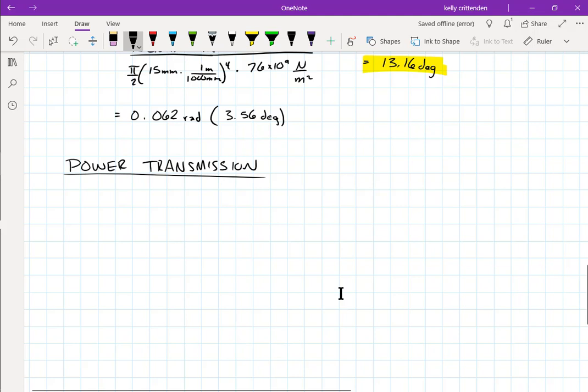We're going to take a pretty simple approach to this power transmission. We're going to assume that power is conserved. If we do want to take into account the idea that there are losses in our system, which there would be, you're not going to have 100% power transmission from your motor over to whatever it's driving. But we'll just say that the machine or the system is some percent efficient. Like it might be 80% efficient or whatever. And so if you put in 100 horsepower, then you get 80 horsepower out. And so we'll just kind of keep it pretty simple that way.